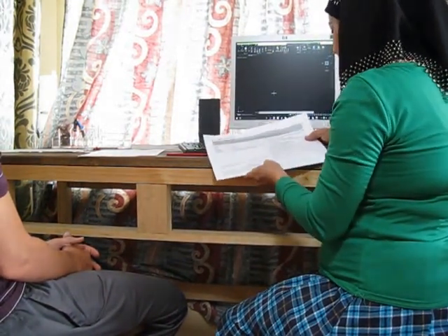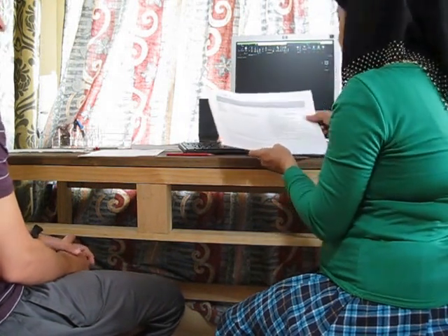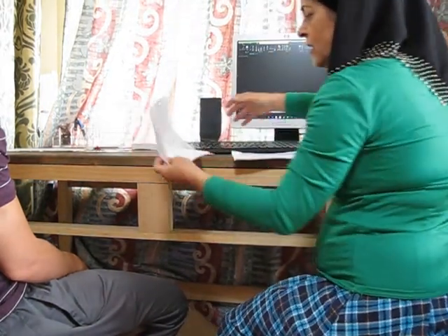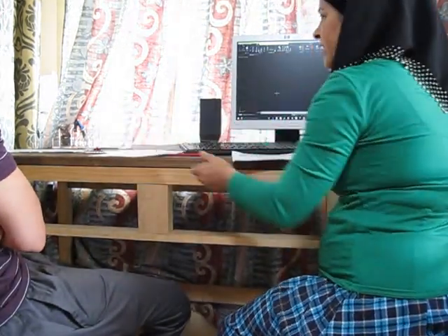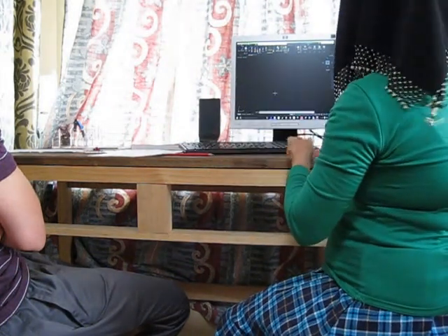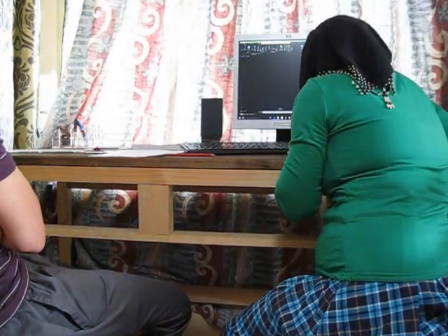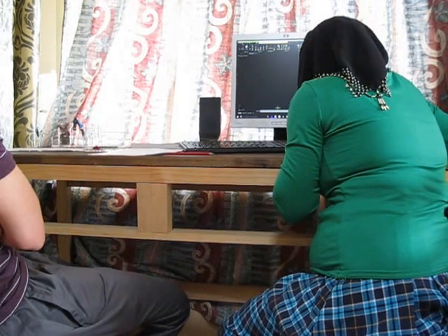Okay, do you remember what the ortho mode was that I taught you? Yeah. Because AutoCAD draws lines with angles. It's like an elastic band that comes and goes everywhere. That is too hard for our measurement. We only need vertical and horizontal lines in this drawing. We do not have that many inclined lines. So most of our drawings are going to be vertical. For engineering purposes, I suggest that we always use the ortho mode.